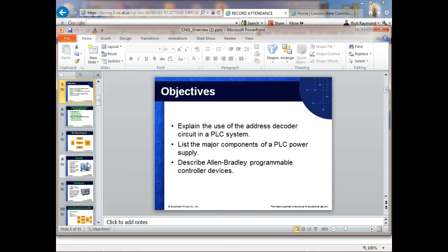Because the ROM, so what can a processor do? A processor can do one thing. What's the one? Run programs. So that means when we turn power on the computer, what happens? We call it a reset. When you power this thing up, it goes to an address in memory looking for an instruction. That's all it can do on its own. And then after that, it is under total control of that program, right?